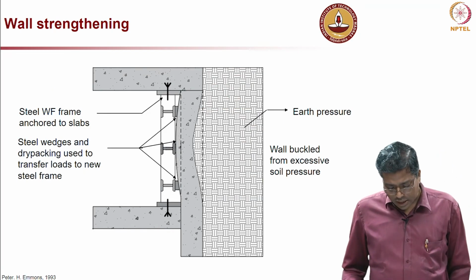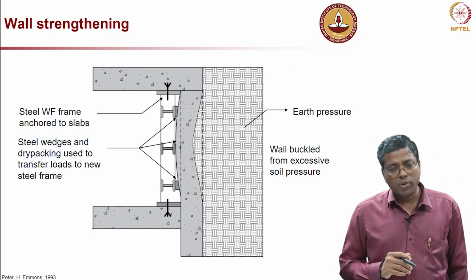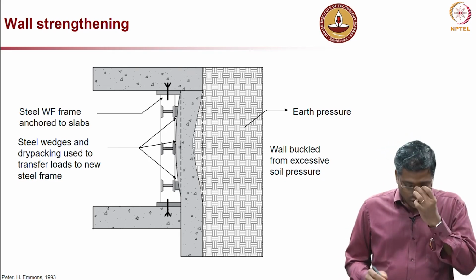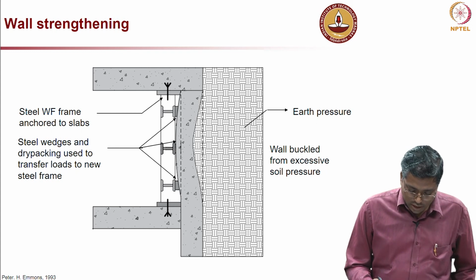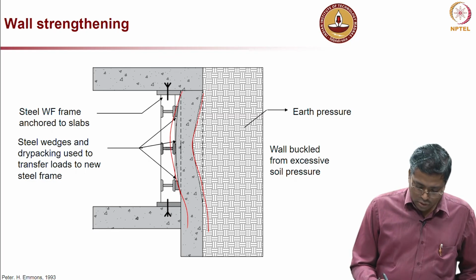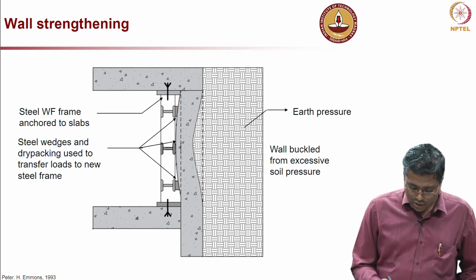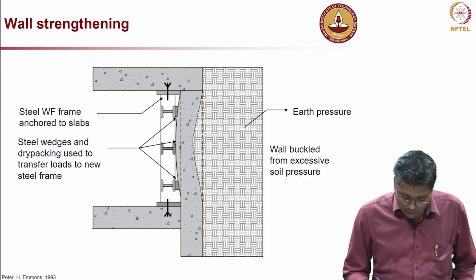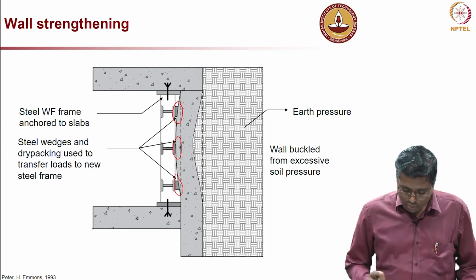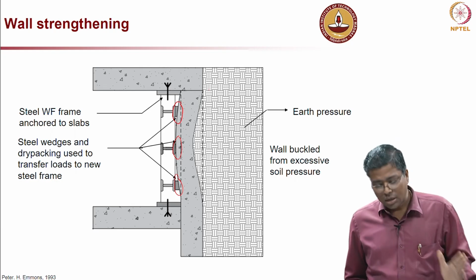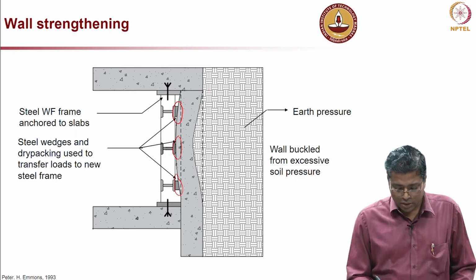So, this is another example where some deformation has already happened. How do we take care of such a scenario, where the vertical element is already bent like this? Now, if you look very closely, the heights of these three I sections are the same, but what they have done is that the filling material between the bent concrete element and the I section has different thickness.